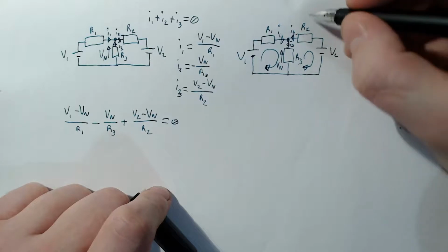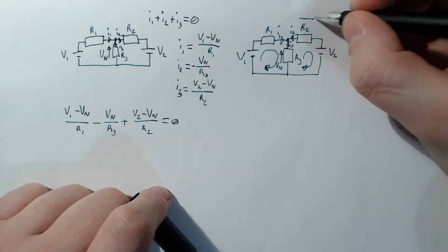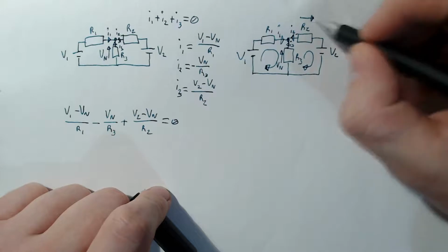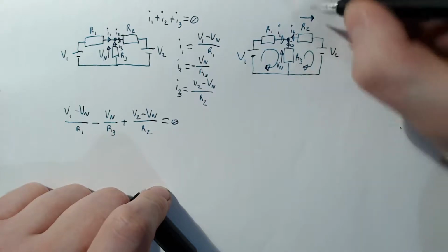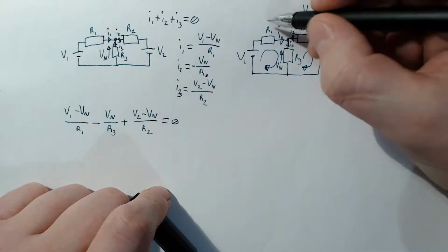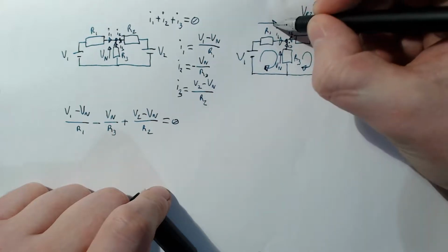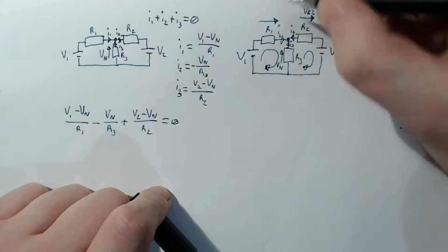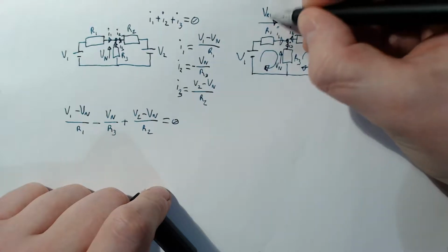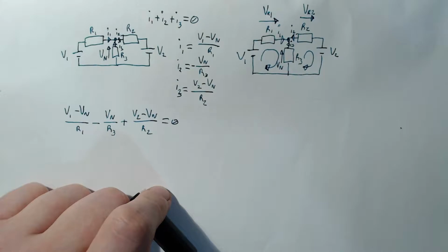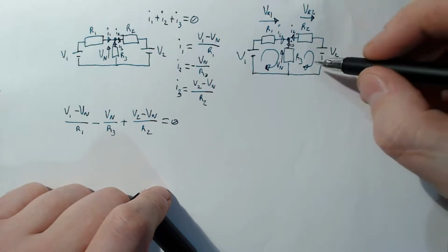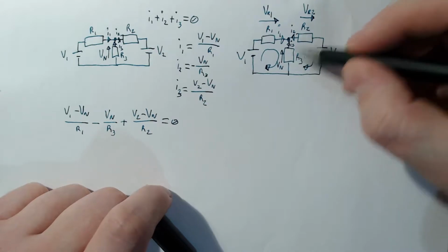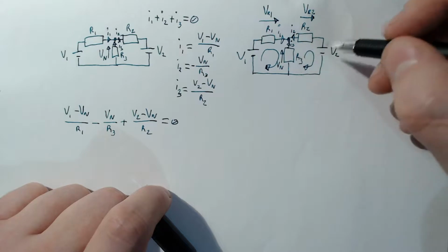Now, the voltage across here, something we've got to be paying attention to. I'm drawing it pointing that way because this arrow is going that way. Those are going in the same direction, VR2, and this voltage going across that way, again, same direction as the arrow, VR1. And that's already called Vn, just there, so we don't need to name that one. So let's write out the equations that sum to 0 of these loops.